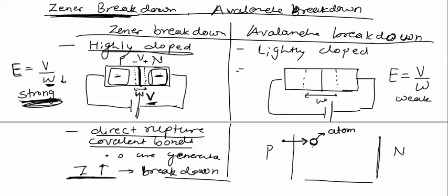If the collision is effective, then after the collision most of the kinetic energy of this electron will be converted into heat, and if the heat is sufficient, more bonds will be broken, that is, charge carriers will be generated, and these charge carriers will start moving under the effect of the applied voltage.